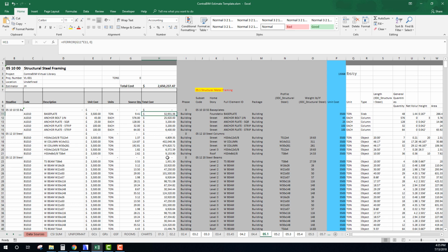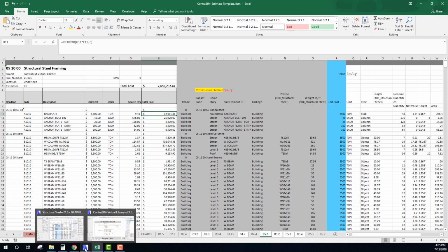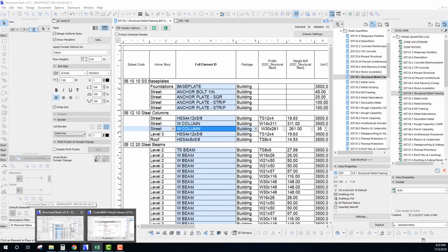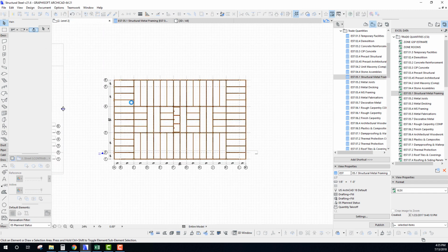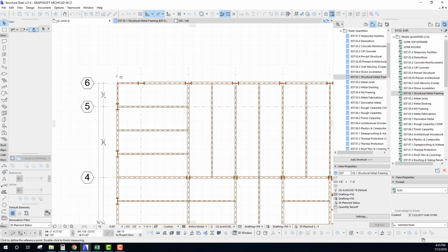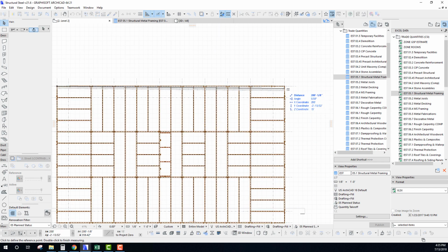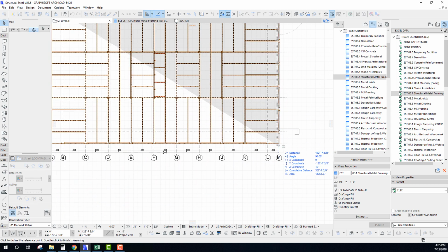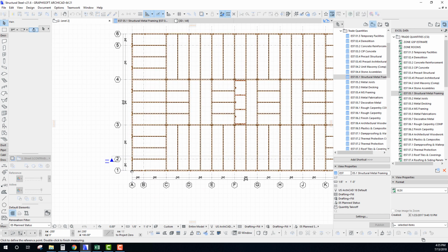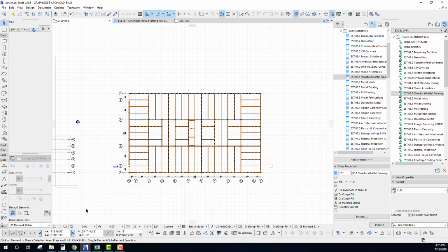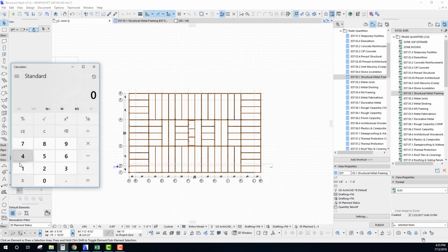million. Let's do a real quick calculation just to see what that turns out to be in terms of pounds, because typically for office buildings like this, I think what's our square footage here? I think we're typically in the range of 14 pounds, maybe 15 pounds a square foot. So we have 24,000 square feet, and we're supporting 3 levels. So let's just do this real quick.